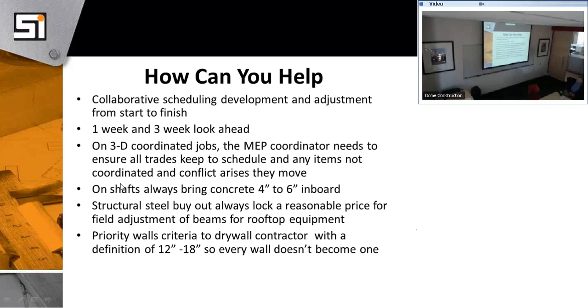Okay. One thing everybody should be aware of on the 3D coordination, some of the things to look out for: graded lines are a huge issue with collisions with other MEP trades, because as you can well imagine, graded lines mean things have to flow through the pipe without pressure. So you're always going to run into some kind of conflict with a graded line.